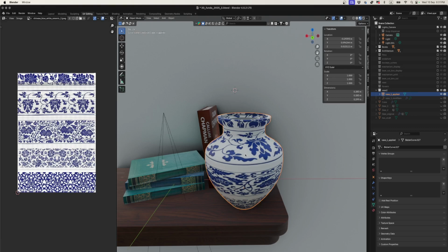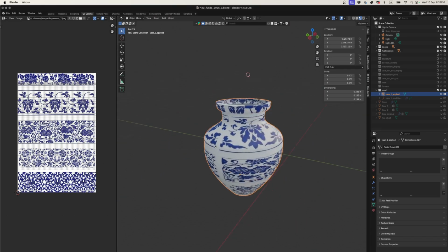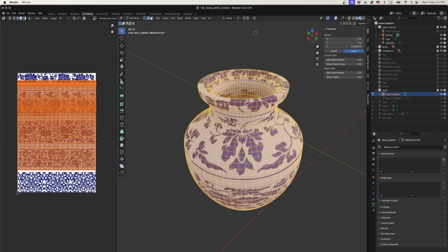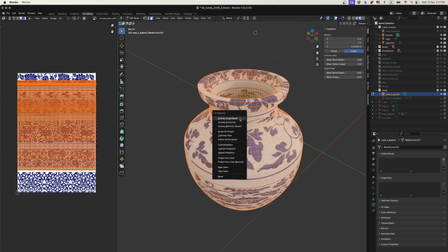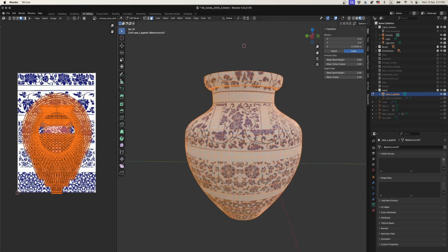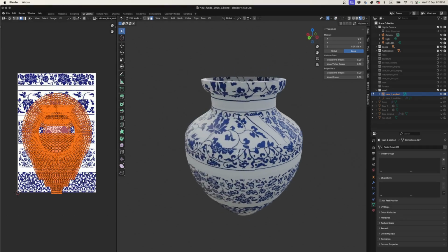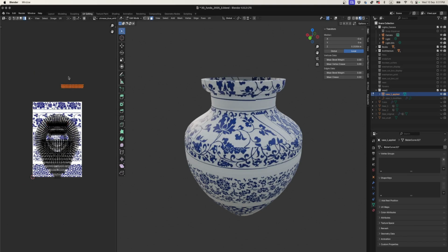All right, so if I'm going to UV unwrap this, I'm going to press the question mark button to isolate select, and we need to project new UVs. If I select all my faces here and I say UV, if I press the letter U to unwrap, and then I say cube projection, we'll get this wacky thing where if I hide these, everything is all mismatched. And if I select the islands, there'll be all these different shapes.